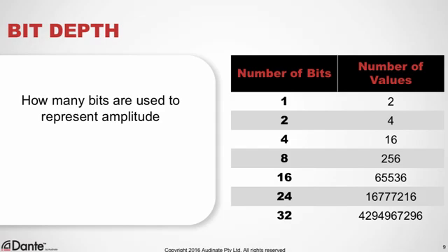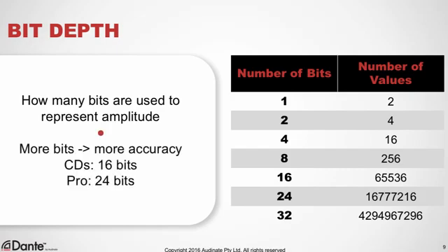Recall those old video game soundtracks, like on an old Atari console? Those were 8 bits of resolution, or 256 possible levels of amplitude. The CD uses 16 bits, and we all know how that sounds. It's really quite good. And that allows 65,536 possible values. When we jump up to 24 bits, we see that we have 16,777,216 possible values.